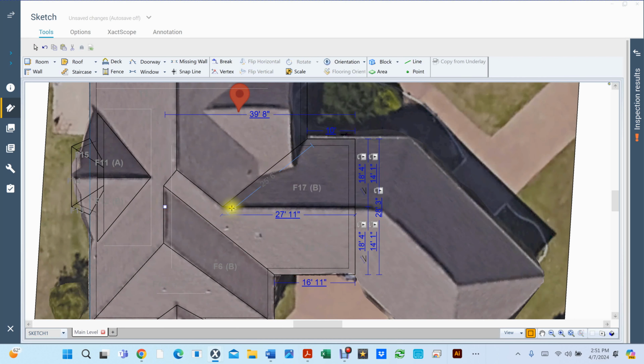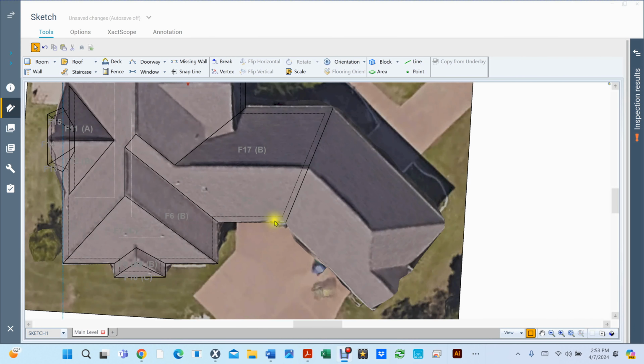Didn't go all the way, but see, it took care of this part. This looks good. This looks good. Now all I'm gonna do is left click here, snap one time. That gets me this part. Alright, so this pull out right here is at a 45-degree angle, and it's a gable and a hip, so we're gonna need another half hip. So if I hit F for roof, hit space, space, space, space, space, I get my half hip.